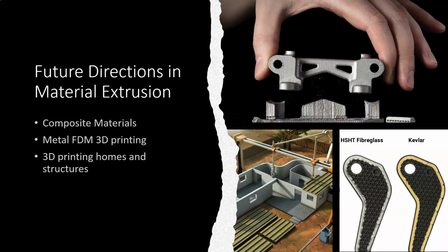inside of it. And then you take it to an oven type system, and you put the part in that oven, and basically you melt away the plastic and you sinter the material, the metal, which is, you basically kind of bond the metal together. And so you end up with a part that is metal, right? And so this is very exciting because you can actually print metal much stronger.